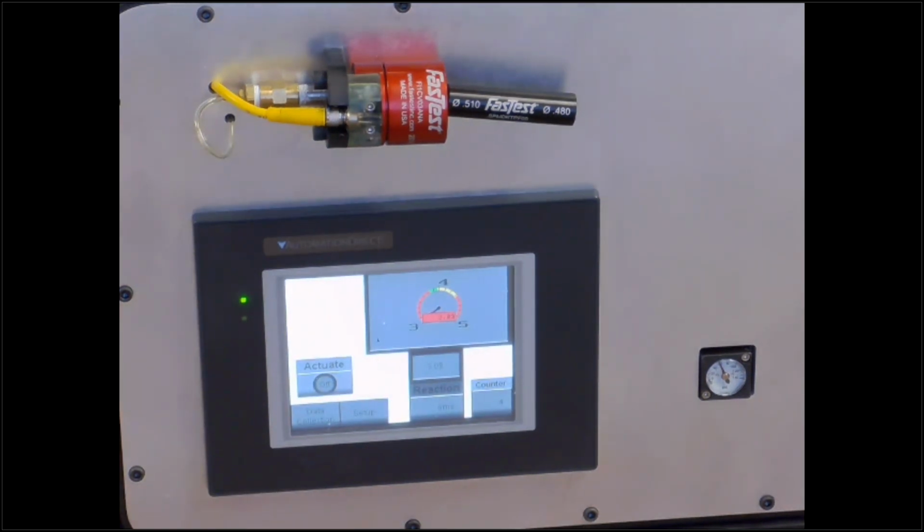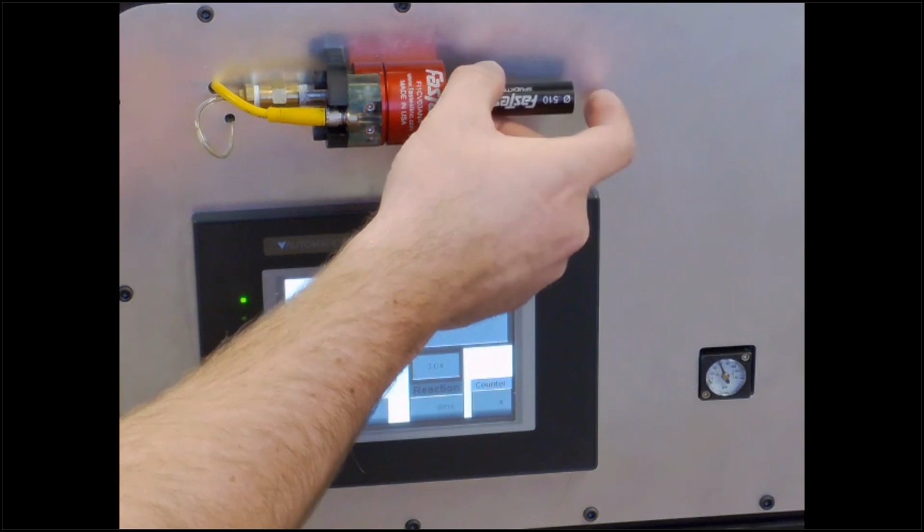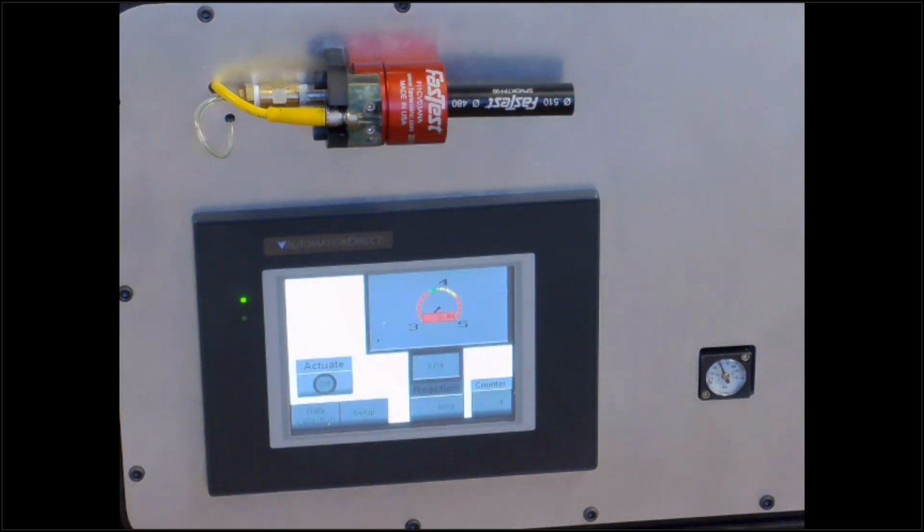Now, let's say we run into a problem. There's some new production lines that came on, and there might be a lower pilot pressure being applied to this pneumatic device. That would actually change the sealing force, and we wouldn't want that in a leak test because you may create a leak path. There may not be enough sealing force for that test application. Another way to simulate that is really under travel. If there's not the same pilot pressure, you're going to end up in a lower zone.